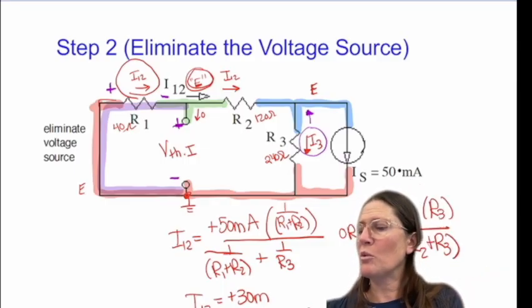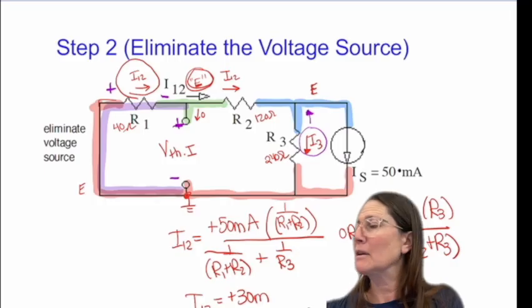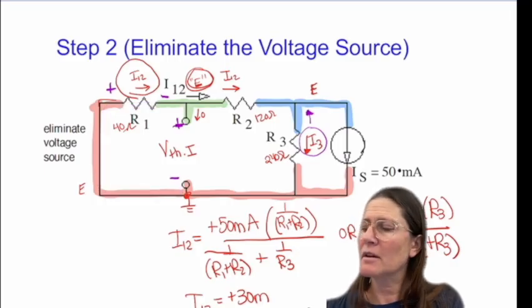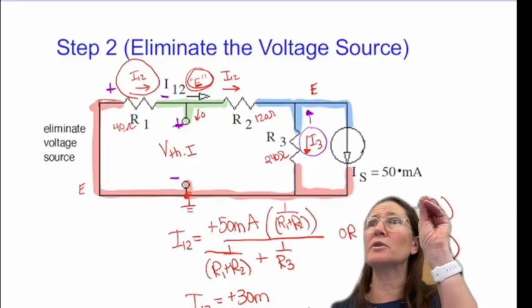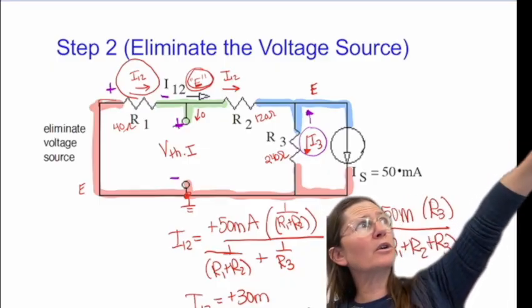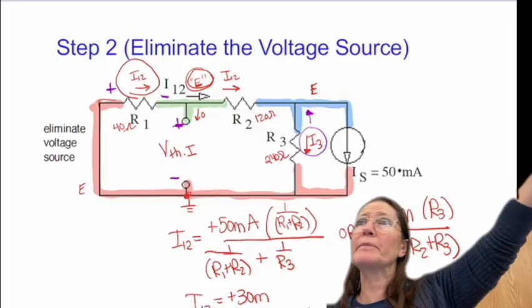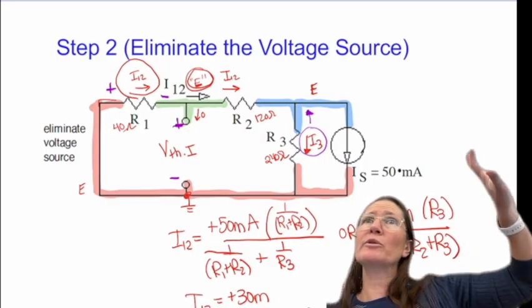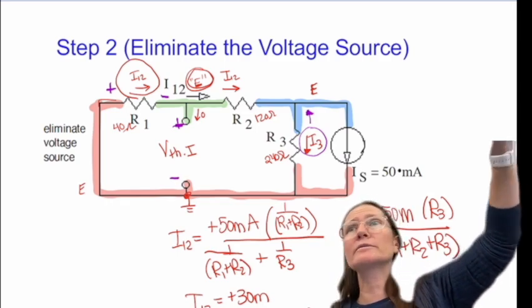So what polarities are on the same colored wires? Okay, so to determine if they're the same or the opposite, it's whatever's on the wire polarity. So you can see on the green, there's a negative on that from the R1, and there's a plus on it from the VTH. That would be opposite. So if you visually don't see it, make sure you're looking at the polarity that it has on the wire.